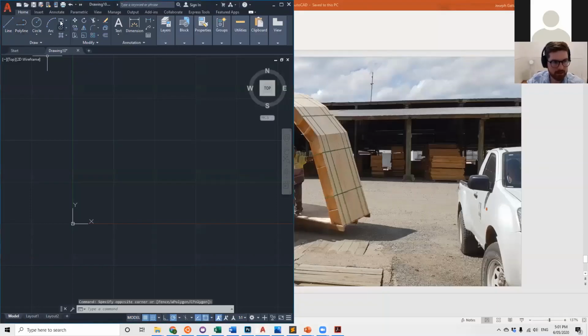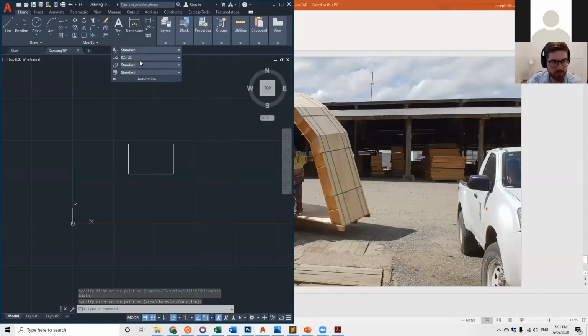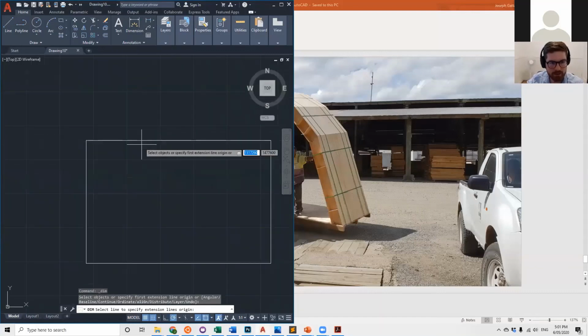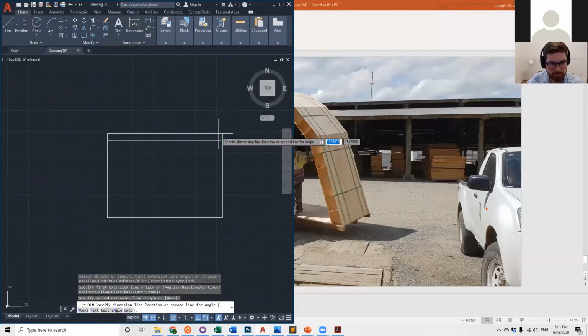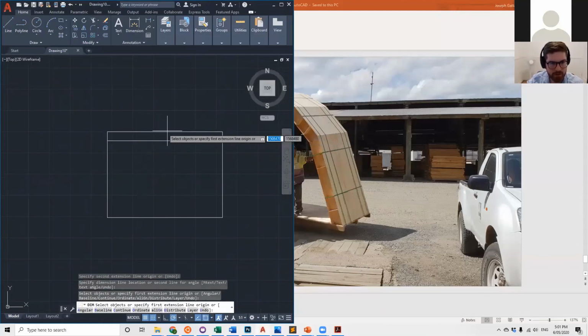Oh yeah, great question from Bella just on dimensioning. That is a pretty key feature. So it is included in the AutoCAD Hitchhiker's Guide, but just to show you quickly, this is the annotation tool. So you can add a whole bunch of dimensions. You can add it by object, so it's selected the entire line, or you can add it by endpoint, here to here. The one catch with dimensions is the size of them.